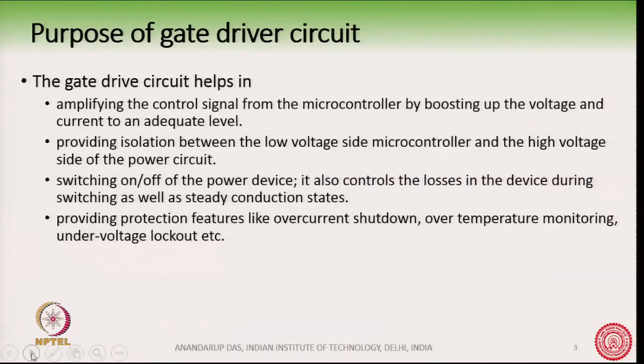Also, often these IO pins are around 3.3 or 5 volt output, and the gate driver requirement for the power devices will often ask for a 15 volt supply.